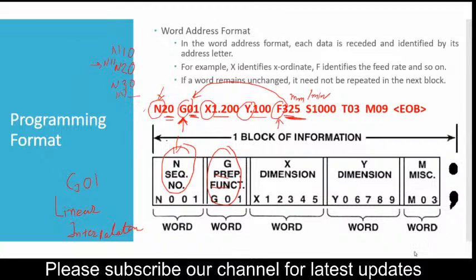Okay, so if I write G00 instead of G01, then the machine will operate at the maximum speed, which is 24,000 mm per minute, the rapid interpolation speed, which is defined while purchasing the machine. It is a machine specification category.